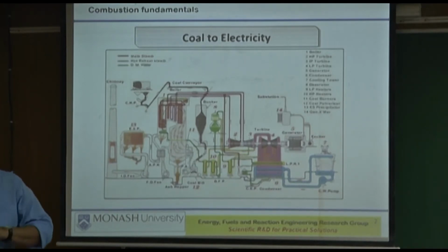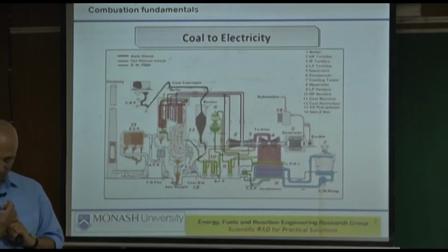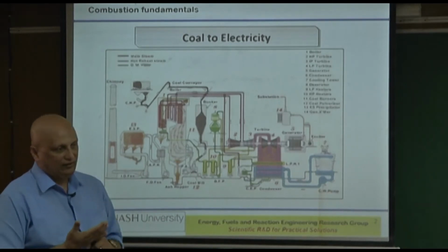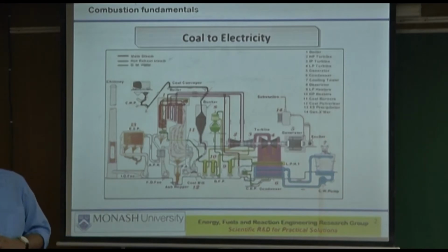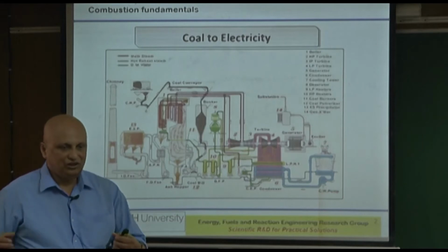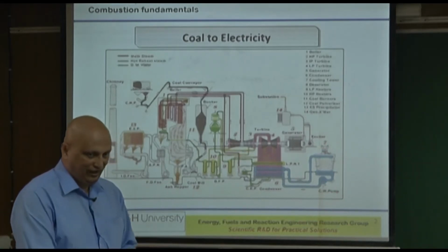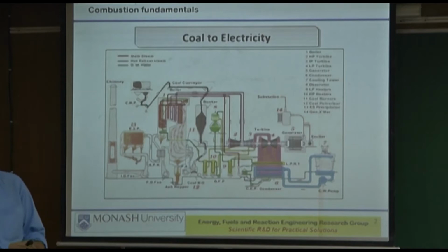Okay, so age of the coal, which means the rank of the coal. By age, we mean oxygen content in the coal, and the very open structure in the coal, so there are a lot of pores, so that the oxygen can go inside the pores and react with the carbon to give you carbon dioxide, rather than reacting with the carbon from the surface, shrinking the core and then gradually eating the carbon from outside in.